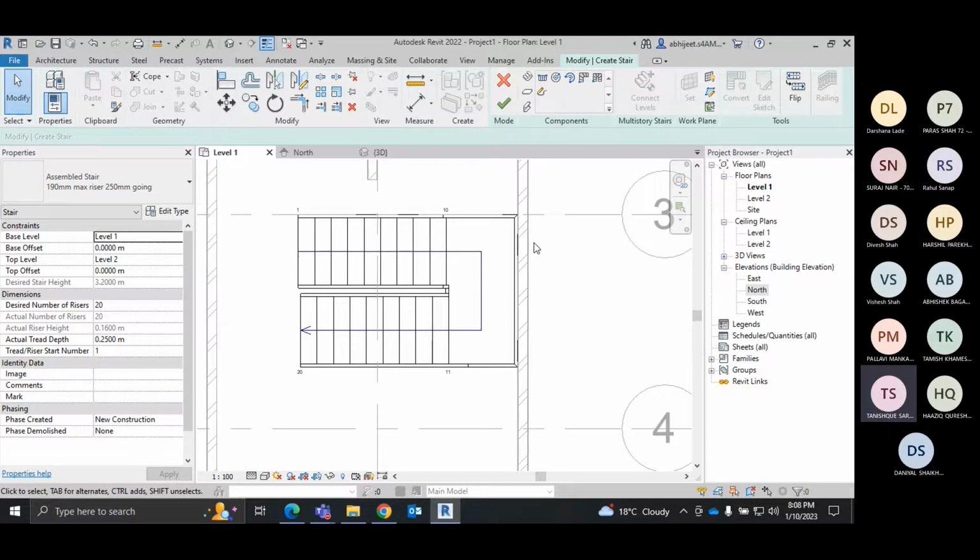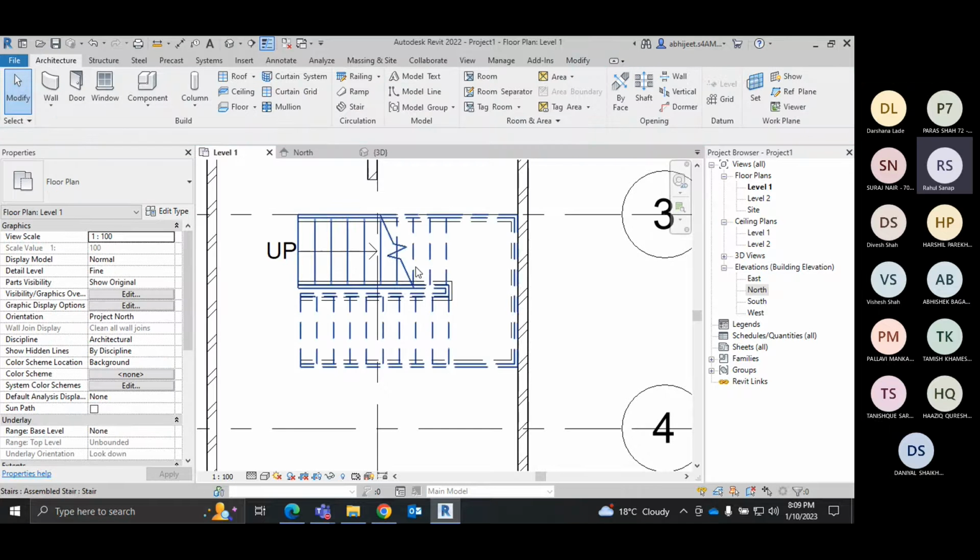So like we select the line to be locked and the reference line, right? No, no. First, you need to choose align. Okay, you need to align which element with respect to what. Okay, so let's say I want to align the staircase with respect to the wall. So I choose the align tool. Then first, where I need to align to, the wall, right? Then I choose the wall surface and then which object, I choose the staircase. So automatically it aligns to the wall like this.